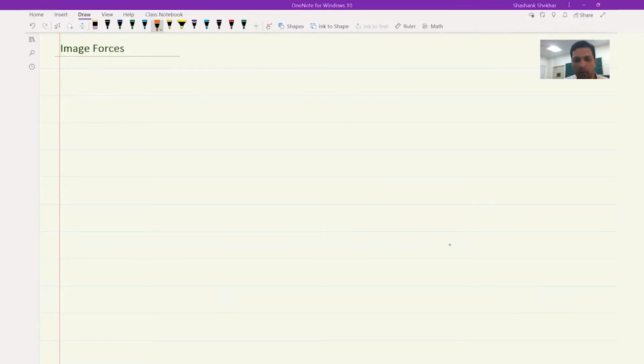So like I said, very near the surface. Let's say you have a bulk material like this, and there is a dislocation somewhere over here, which has the slip plane like this. Then because there is relaxation near the surface, there are some forces acting on the dislocation which tend to move it out. And how do we find that force?